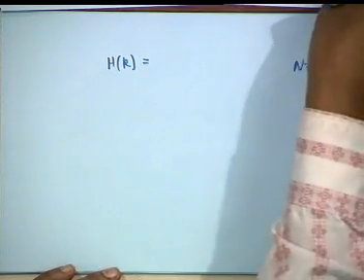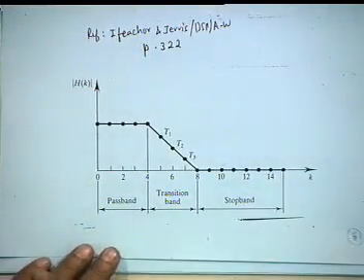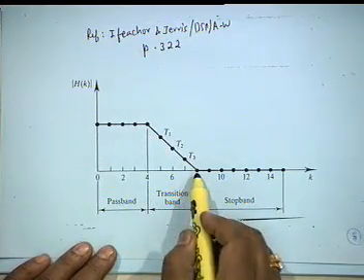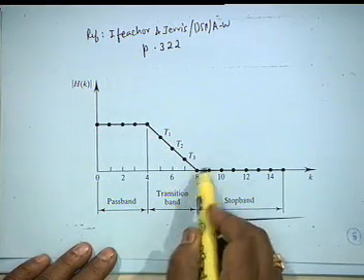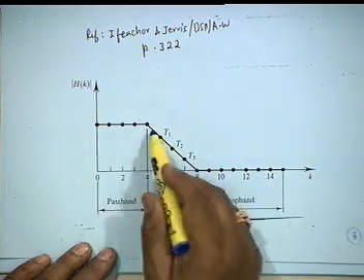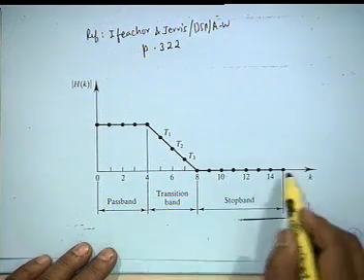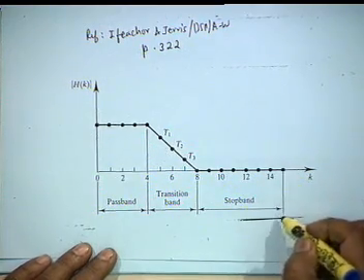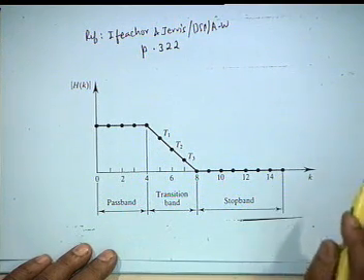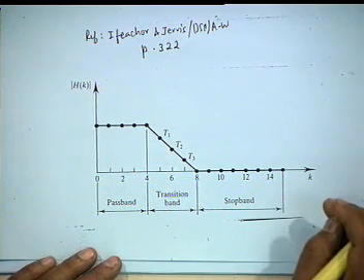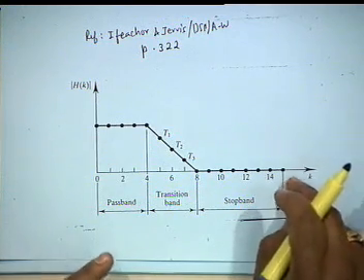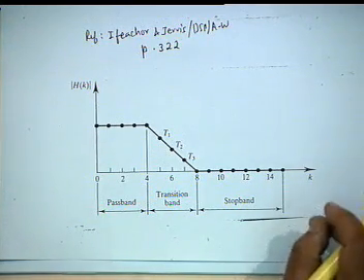Not quite. You know, what we require is, if we take capital N as odd, only these samples, right? We don't require anything beyond this. Now, if this is the pass band and this is half of the, this corresponds to pi, therefore the number of samples would be 29, agreed? 15 times 2, 30 minus 1, 29.